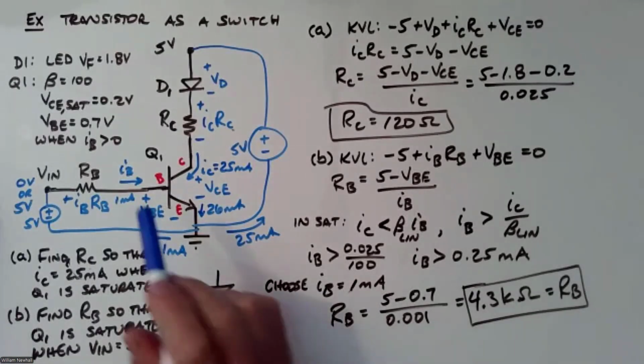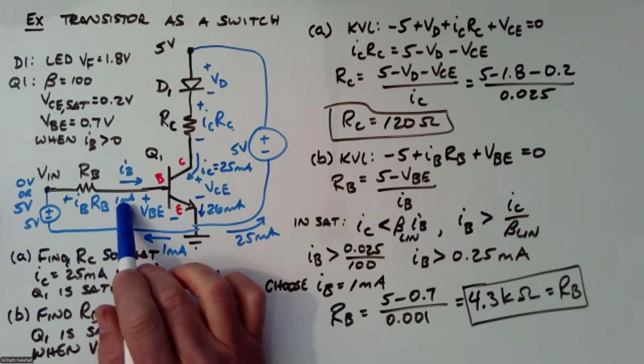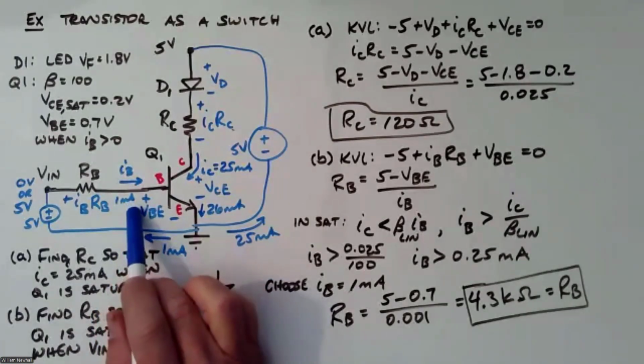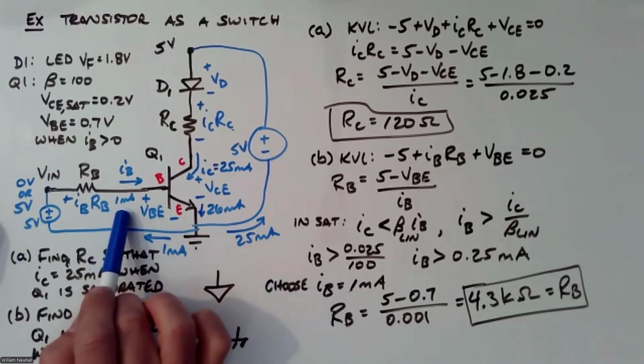Someone says, is there a way we can calculate the most efficient base current? Well, yeah, there's probably in the data sheet a minimum value of beta for the conditions under which you expect to operate: the temperature range, part-to-part variation. There's usually a typical value for beta and then a minimum value within their specified temperature range. So you could just use the minimum value.